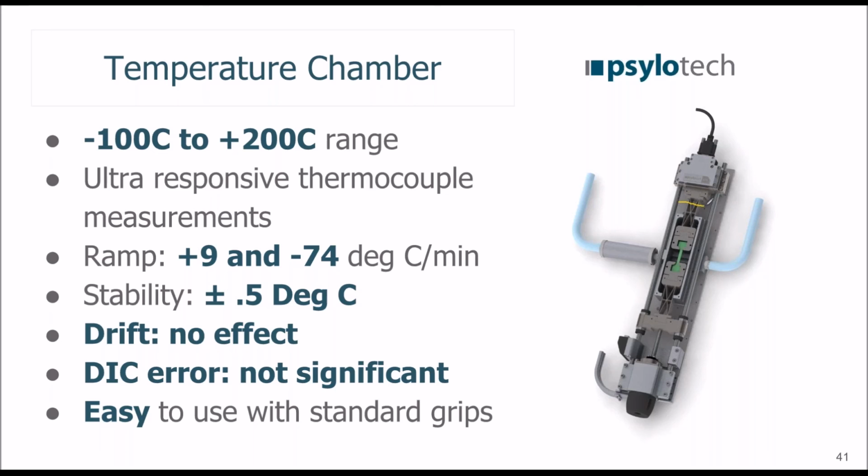It goes actually between, this is the 1.6 kilonewton. The chamber is kind of here between the shafts. So it sits within the normal footprint of the actuator aside from the heating cartridge here on the side. It makes the actuator a little bit longer, or the whole load train a little bit longer in total, but no wider or taller. And actually we still are able to fit the microscope into view the specimen here. So it's compatible with DIC, microscopy, and it just fits in with the way the load frame is suited now, allowing all the same sensors.